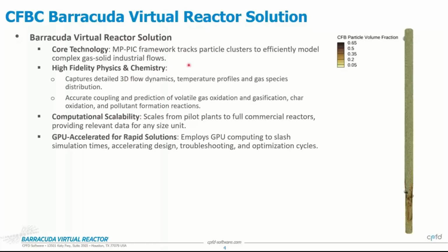The idea is that inside of this framework, we are actually tracking particles. These are numerical particles or computational particles, also referred to as clouds. And we're dynamically tracking a four-way coupling between the particles as well as the fluid. By four-way coupling, I mean that both the particles and the fluid phase can exchange mass, momentum, energy back and forth.